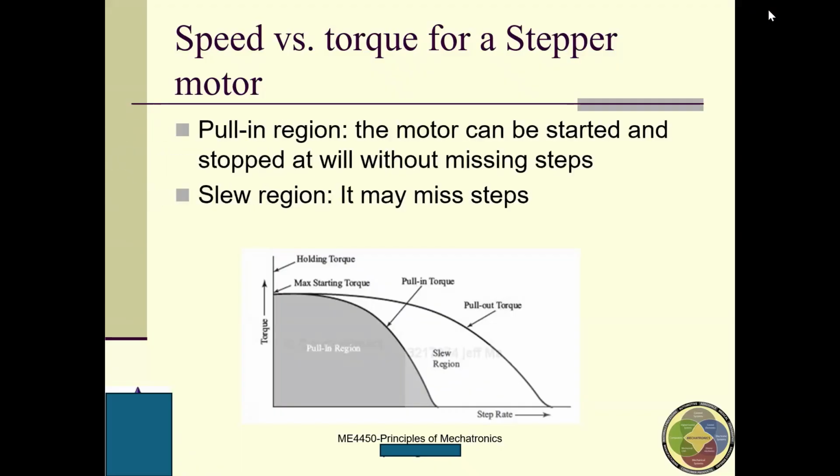So here we talk about a lot of the good things about this stepper motor. But some students might ask, are there any drawbacks? Are there any limitations of this guy? Yes. The limitation is that sometimes we might miss some steps. Sometimes we ask this guy to go 45 steps, but sometimes this guy will not follow your instructions closely. It might go 44 steps and stop.